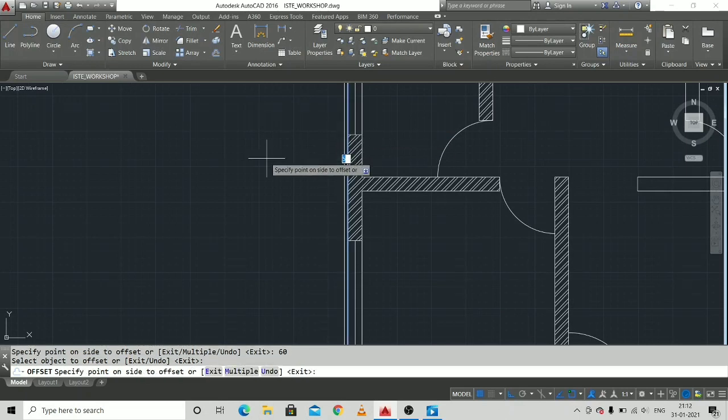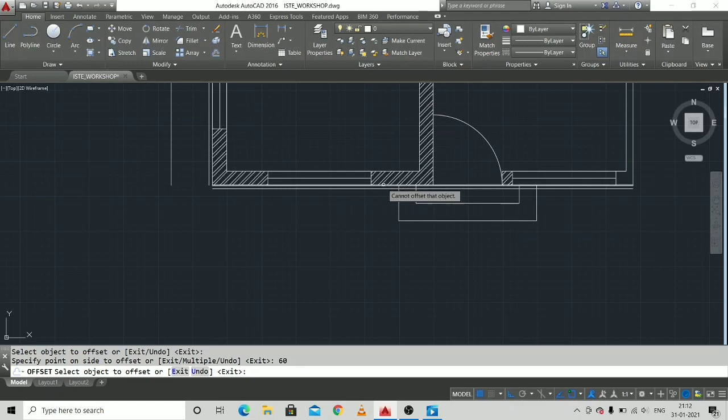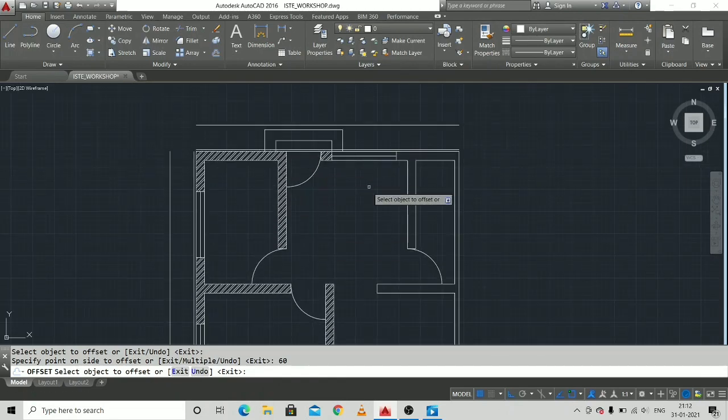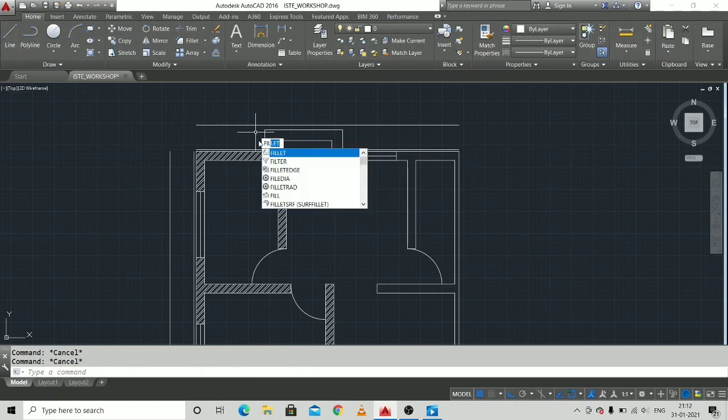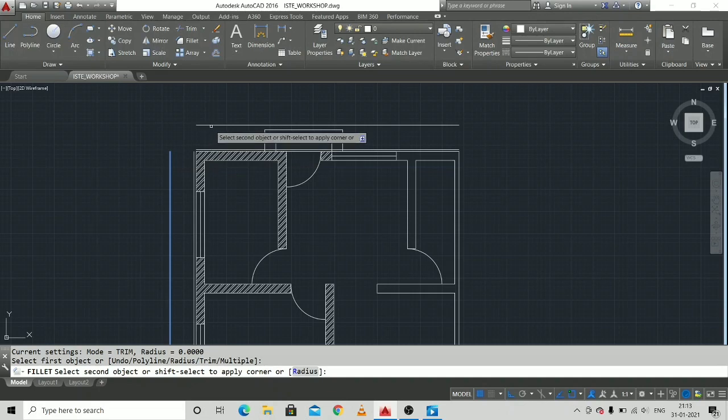I am doing this so as to have the projection of the roof of my house. And the inside projection of 5 centimeter was the projection of the basement of the house because of the plinth. So I am again using fillet to fill my gaps at 90°.